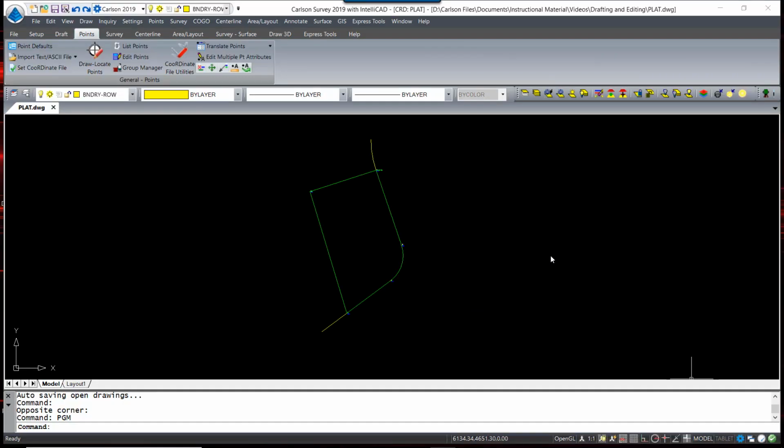We can now start paying attention to the other data in this survey, but before I continue, I'm going to reset my drawing orientation so it's a little bit more perpendicular to the screen. Right now, north is straight up, but I would like to rotate this property line just a little bit. I'm obviously not going to rotate it using an AutoCAD rotate, which would alter the coordinates.